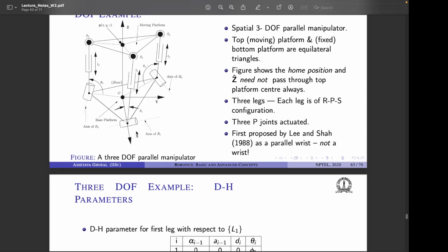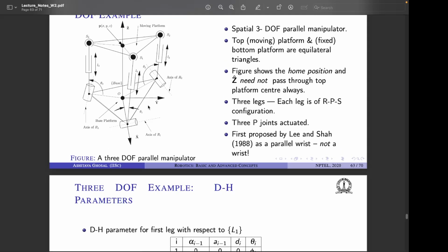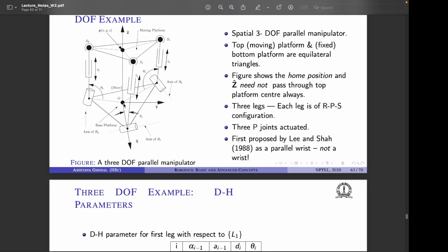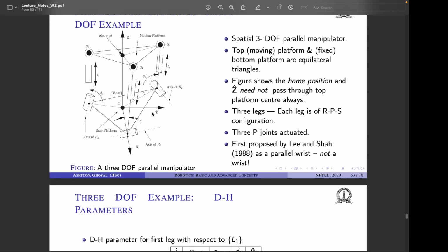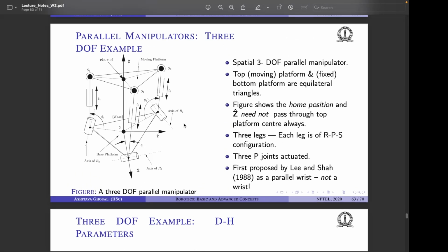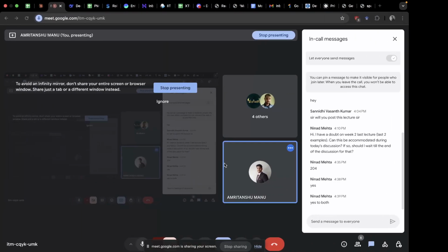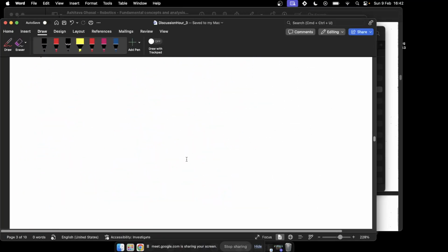And so theta 1, from the DH convention, is the angle between the x axis of the two consecutive frames about the z axis of the joint that we are talking about. So the base x is here, and the other x is along this. I think I will need to draw something. Let me just snip this from here, and let me just put it in there.